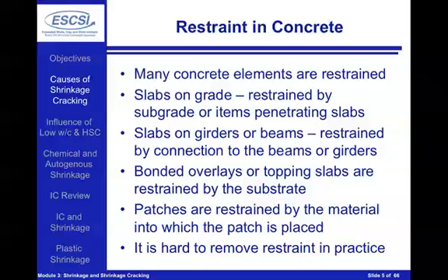The concrete is going to want to move around due to temperature and moisture changes, but the substrate will prevent or restrain that from happening. Patching materials, for example, are going to be restrained by the parent material that the patch is being placed on, so there are very high levels of restraint. In many cases, it's really hard to remove this restraint in practice, so what we really want to try to do is design our concrete so that it shrinks less, so that it will have less built-in stress overall in the system.